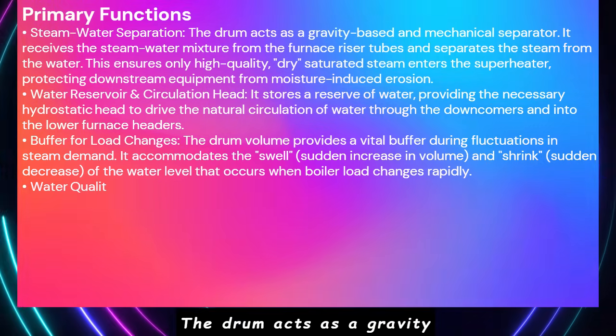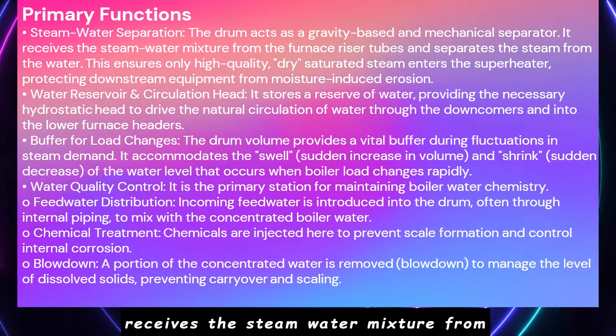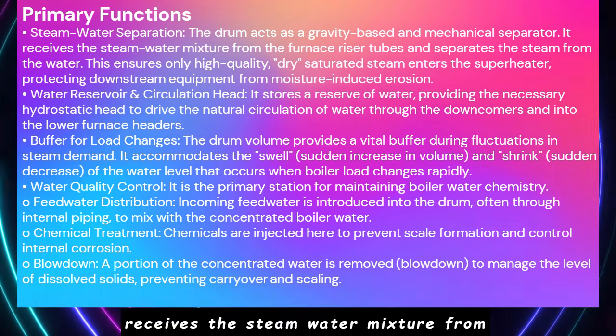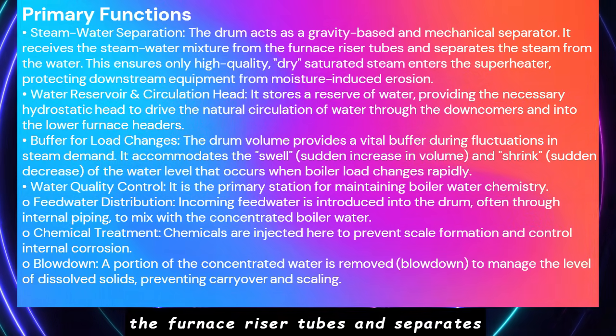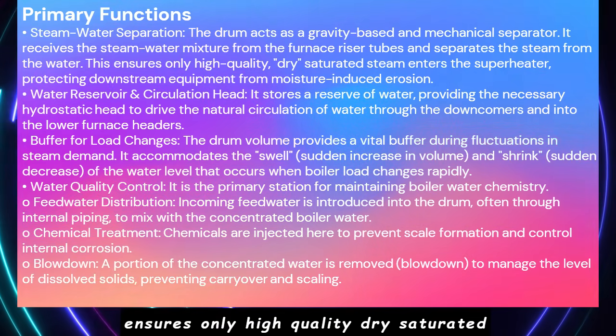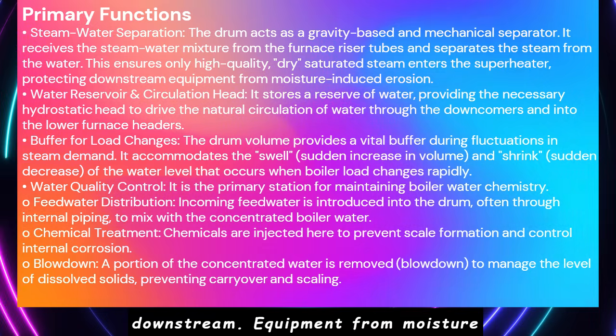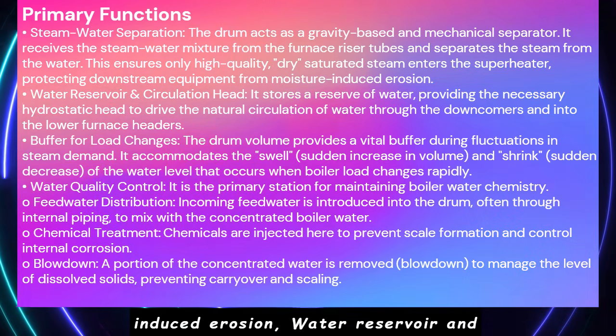Steam water separation. The drum acts as a gravity-based and mechanical separator. It receives the steam water mixture from the furnace riser tubes and separates the steam from the water. This ensures only high-quality, dry, saturated steam enters the superheater, protecting downstream equipment from moisture-induced erosion.